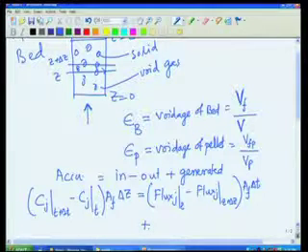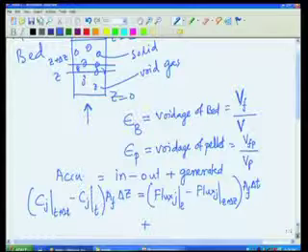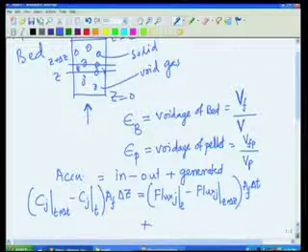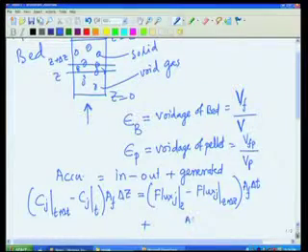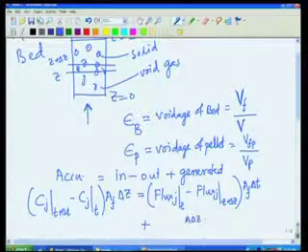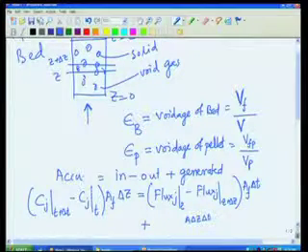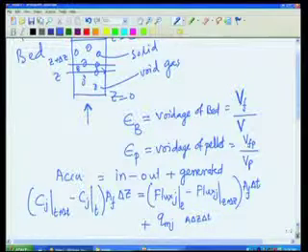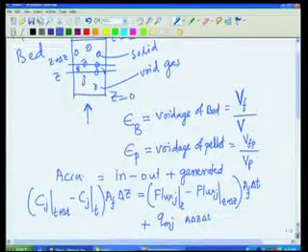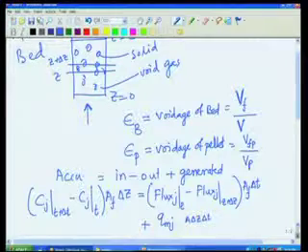Generation, typically if you recall, we denote it per unit volume of the reactor. So, let us say the volume of the reactor is A delta Z, A is the cross section area, in time t, and for the time being I am just going to put Qmj as the rate of generation of this species J. Now, you may wonder what is this Qmj.